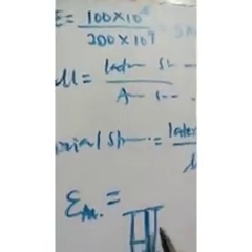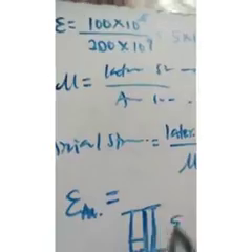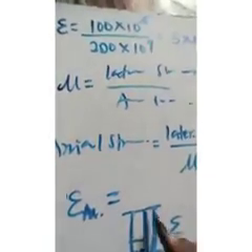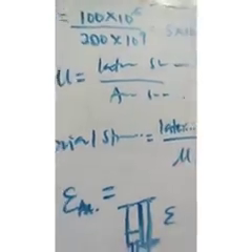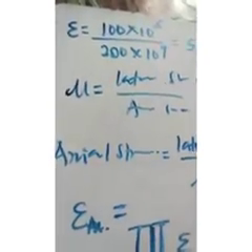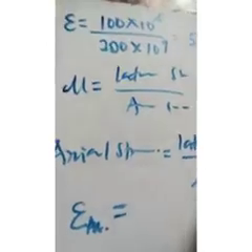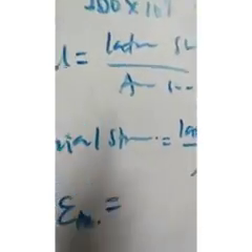The word here is very important. So this side is your strain. So the lateral strain, you can see it's this side, the elongation part for this side. So if I'm going to solve this now, I'll just put the lateral strain. So in this context, if I find this lateral strain now, my axial strain will be equal to my lateral strain over Poisson ratio.